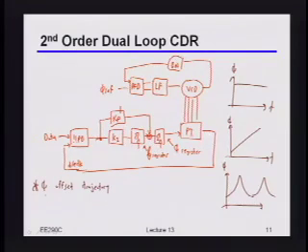So if you have a spread spectrum design, you'd want something that would not only figure out what the frequency offset is and what the nominal phase offset is, but in fact what the spreading frequency is, what the spreading rate is, and so on and so forth. Okay? There are not too many systems that you will deal with that have to deal with that. But it's again something important to know about because it gets to this general principle of designing your CDR loop so that it indeed tracks whatever the trajectory of your input is doing. Okay? Any questions on this before we move on?